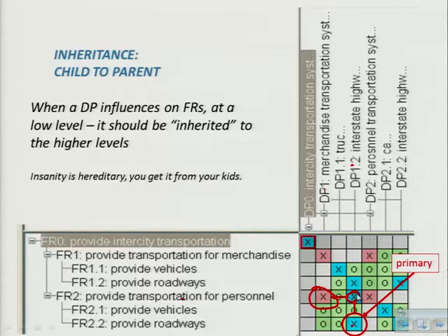But in any case, now as we work through this whole thing with all of the coupling complete, we can see that this is now a completely fully coupled matrix. And they turn pink because there's no way to resolve that. So you can find the little click and click on decouple this, which is provided in Aclaro, and you'll notice that it can't decouple it. So you're stuck with this coupling, and you notice that it's a bad design.